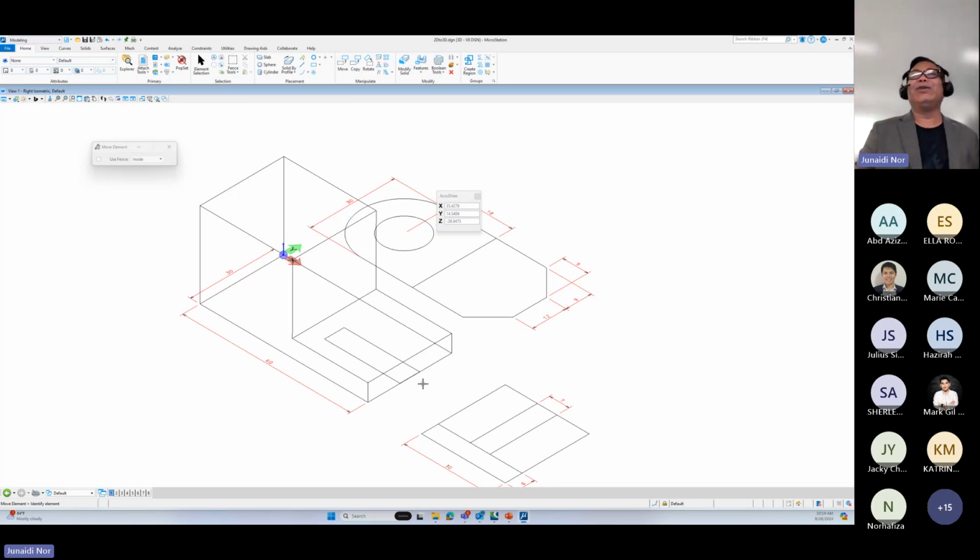Because we are used to one CAD application that is so easy. Click, click, click, click, click. Everything goes there. But now with Microstation, you need to follow the rules. So when you have two objects here, right click to select the other object. Okay. So confirm, then click the left button to accept. Always remember, left button is always accept. Right button is always cancel. Okay, accept.